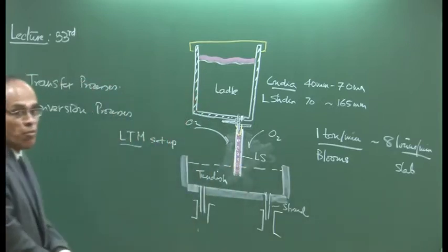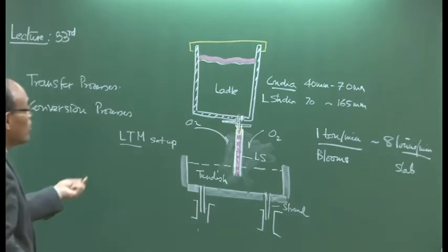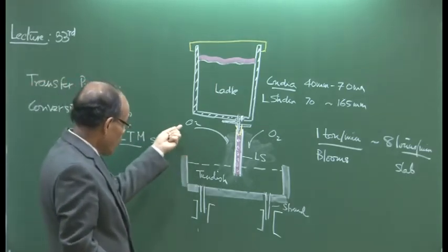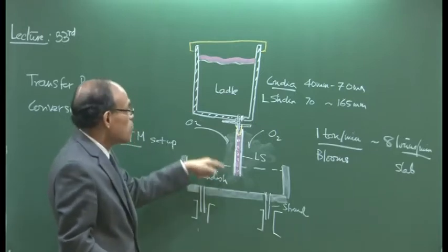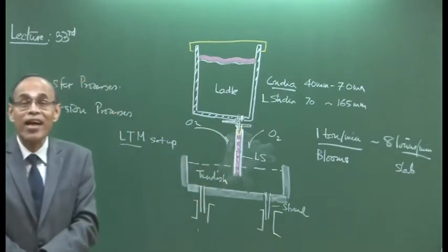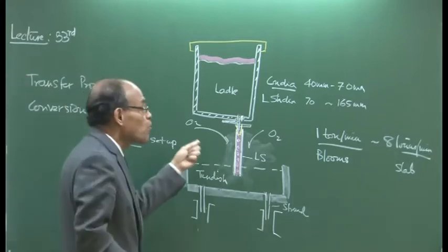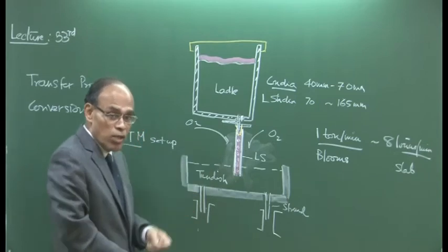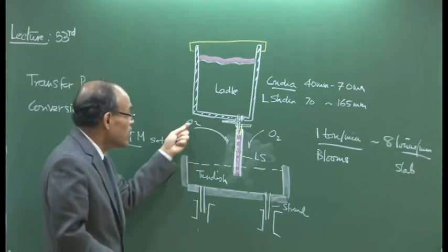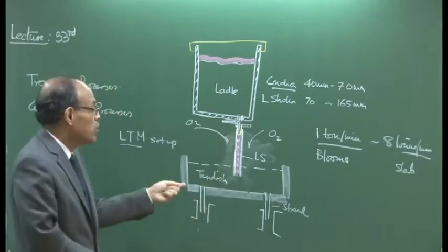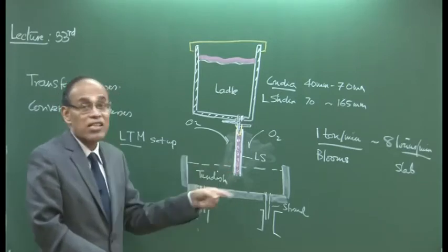That is one scenario, at low air aspiration rate. This phenomenon of atmospheric air getting into the shroud during the transfer process is termed in the literature as air ingression. This air ingression needs to be stopped at any cost, to the extent possible, if we want to produce quality steel, because the oxygen thus ingressed into the molten steel, which is virtually killed, makes steel susceptible to oxidation.